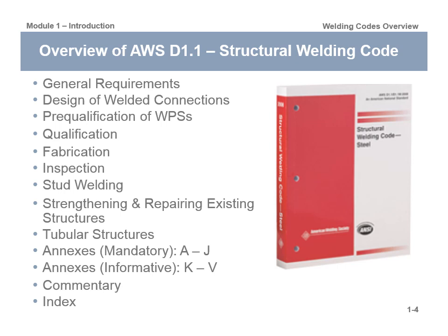Clause 3 is pre-qualification of WPSs. That's where we pre-qualify WPSs. There's a whole list of materials that have been welded so many times with certain specific filler materials that the American Welding Society just said, all right, this is pre-qualified. If you do this, this, this, and this, you don't have to qualify a procedure. You follow these rules, you can pre-qualify it. Then you've got qualification, clause 4. Qualification covers anything that you can't pre-qualify, and it covers the qualification of people.